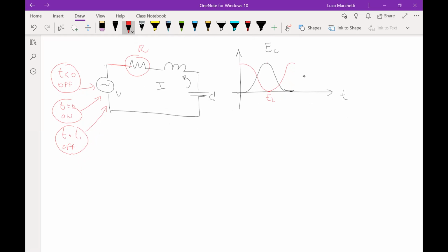You are consuming energy. So what will happen is that it will not happen as I said before, but rather something like this. The energy that the inductance and the capacitance exchange reduces in time, because little by little the energy is consumed by the resistance, which becomes heat, okay. So again, this is why this R is very bad for the resonance circuit.